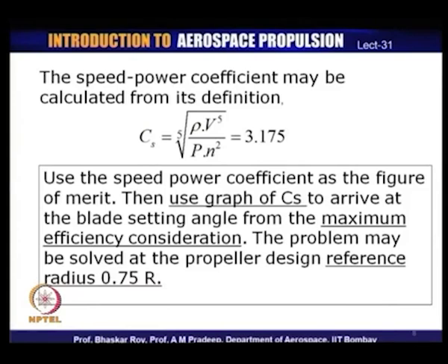So, we shall use this speed power coefficient and the speed power coefficient plot or graph to arrive at the blade setting from the maximum efficiency consideration. We are assuming that we will solve the problem for maximum efficiency of the propeller for this particular operating condition and the blade setting which we will be arriving at.